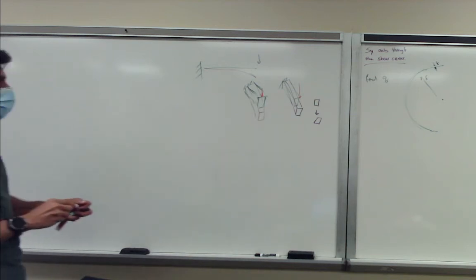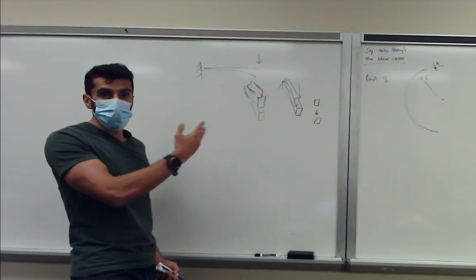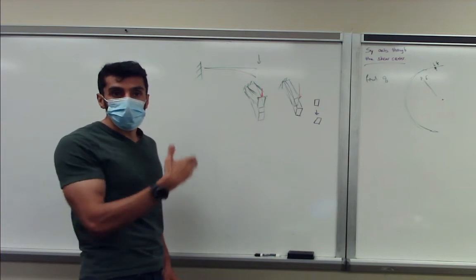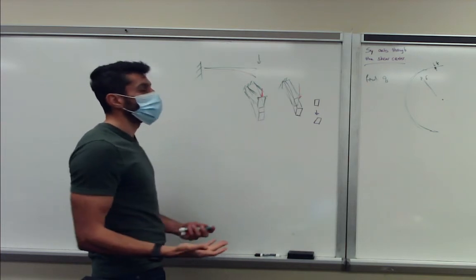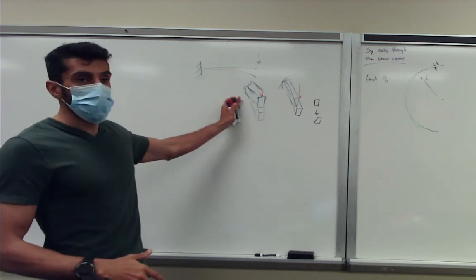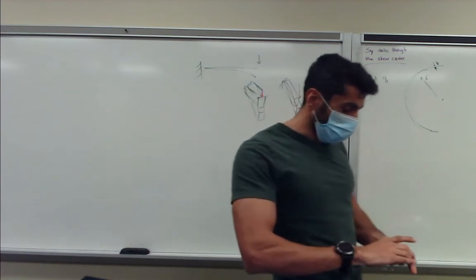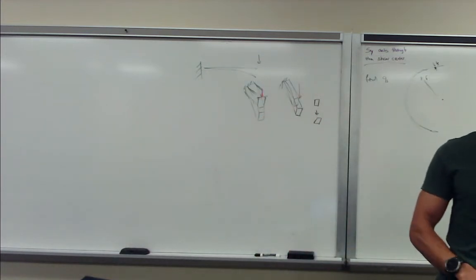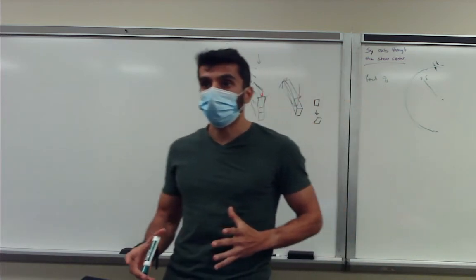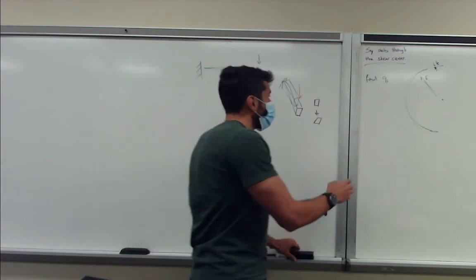And the reason for this is this was applied in a symmetrical axis, so it got basically no twisting, and this was not applied in a symmetrical axis plane. Or, a bit more correctly stated, this force was applied in the shear center, this was not. So the shear center is a location where we can apply a force, and where we get only bending and no twisting or other forms of deformation. So let's delete this.